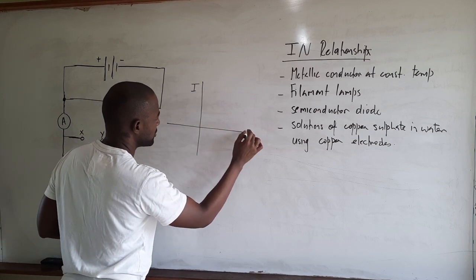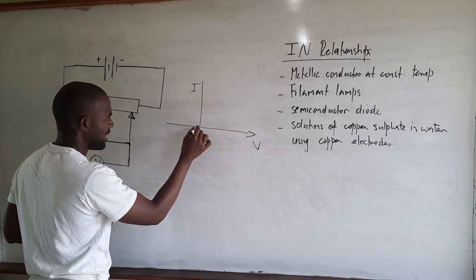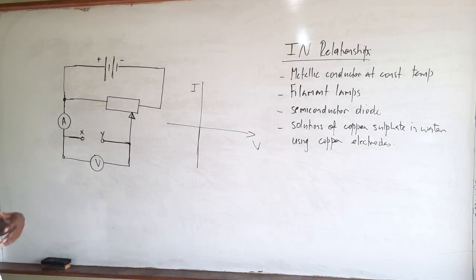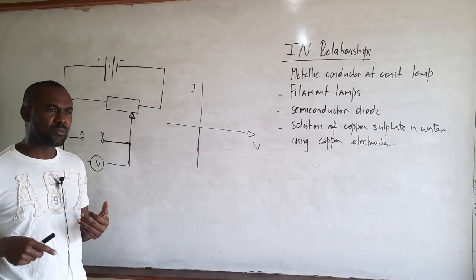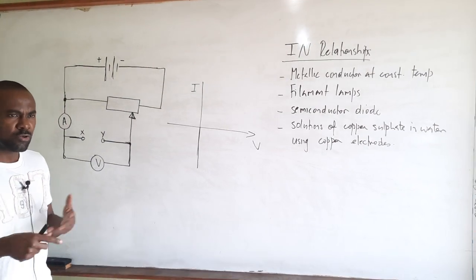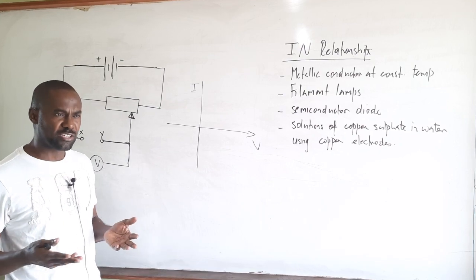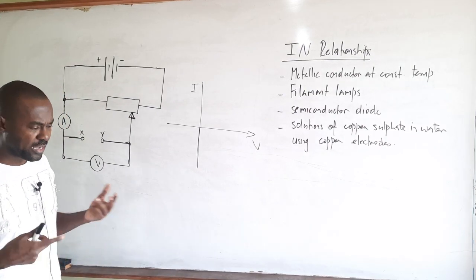And the IV characteristic is of course typically a graph of current plotted against voltage, right? So the IV characteristic of any component is a graph which shows how the current flowing through the component varies with the potential difference, or the voltage, across the component, and it is normally done in what we call forward direction as well as reverse direction. What exactly does that mean?